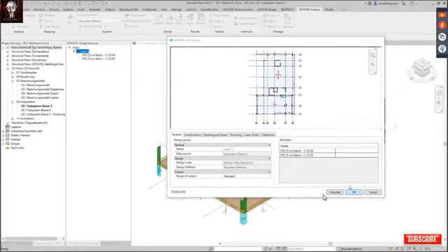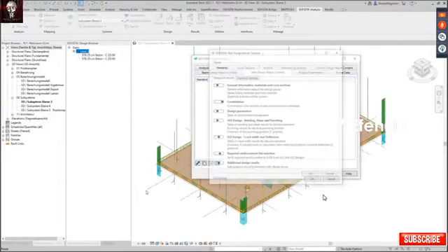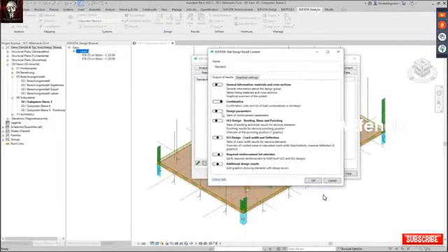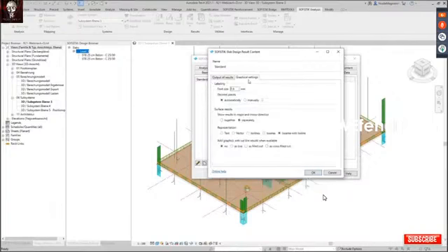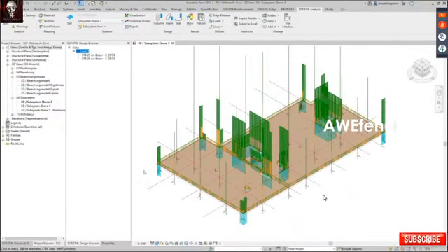What is also new in 2021 is that you can adjust the content of this report. For this, you have here in this dialog the definition of the result content for slab design. You can ask to have, for example, more information. Here, I just want, for example, to have more punching result or detailed punching result for all positions. And you can adjust the graphical settings. So how my graphic will look like in the report. Interesting is here, you can also say, I want to have display of cut line results in my report, if I have some. So I just activated this one.